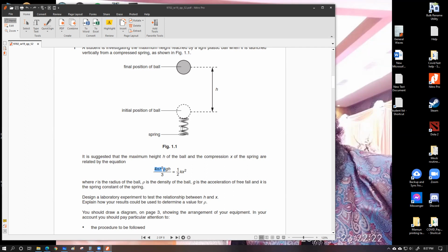But whatever you do, you have to have an achievable and easy to make sort of release device. Release device means that the spring should be in a compressed state that you should do with proper measurement. And you should do that with proper care, so that you can take a good measurement of how much the spring's length has decreased. You should have a good way to measure that. And also you have to hold it in that position for a while,